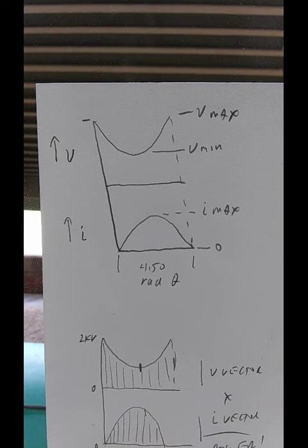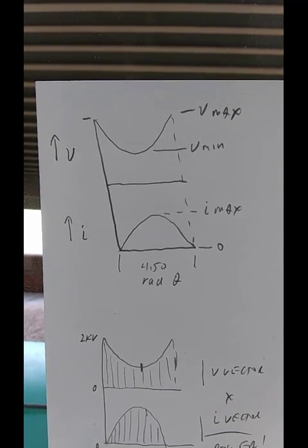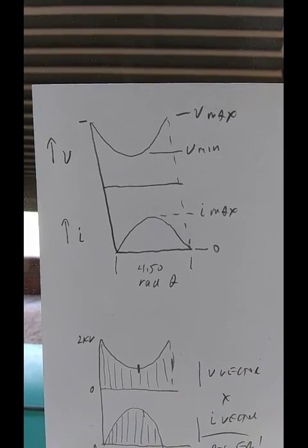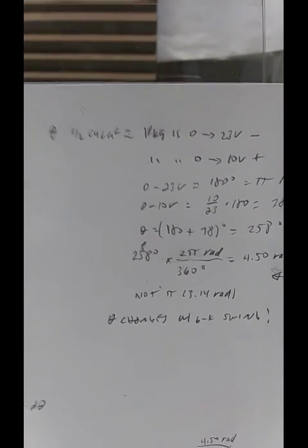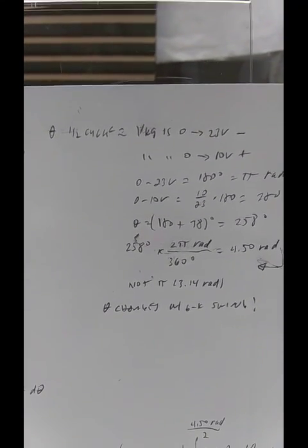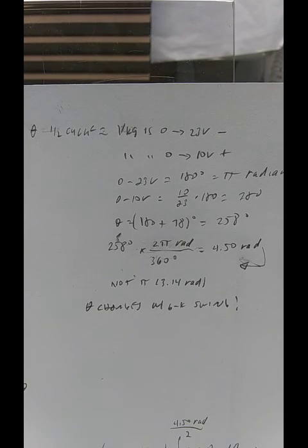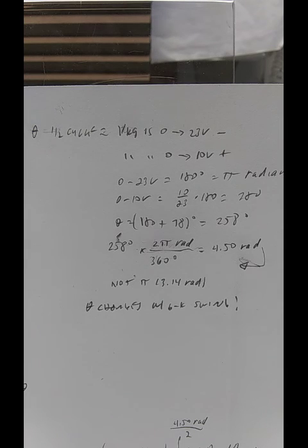The drive signal swings also 10 volts the other direction, so suddenly, with a low drive, the input cycle is not pi radians, it's not half a cycle, it's more than half a cycle. This is not so important for finding a formula for average plate voltage, but that figure will be inaccurate if I use it for this case.